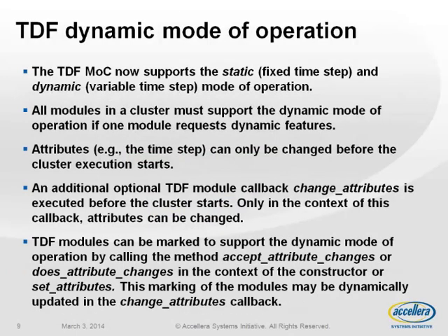The TDF MoC in SystemC AMS 2.0 now supports the old static mode of execution where rates, delays, and time steps were constant, and the new dynamic mode of operation. As I said, all modules have to support this dynamic mode of operation by setting a flag, and the attributes have to be always specified before the cluster execution starts again, so that the full schedule will be executed. Like during elaboration, the TDF attributes have to be set in a special callback called set_attributes. The changing of the attributes will then happen in a new callback, which is called change_attributes.